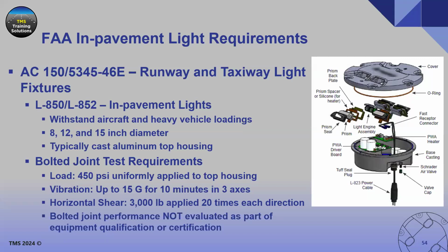Again, designed to withstand aircraft and vehicle loadings. They come in 3 different sizes that are defined. The top housings can be made of any material, but they're typically made from a cast aluminum. And then there's a whole long list of test requirements for this equipment, but again, the ones related to the bolting joint and the fixturing onto the base can are a load test, which is the same load test that's conducted on the base cans themselves, the 450 PSI, uniformly across the cover.